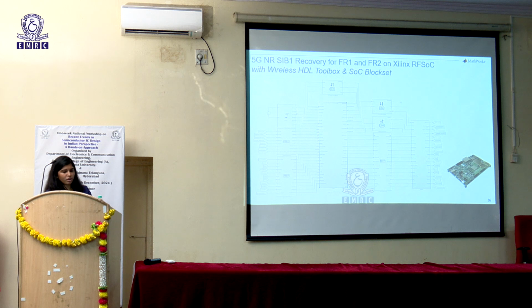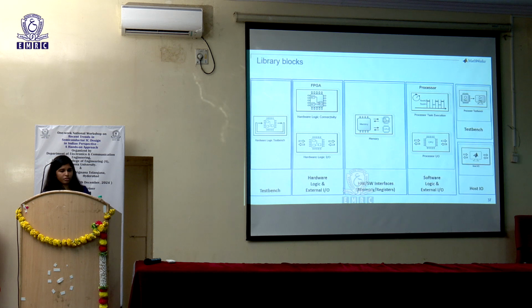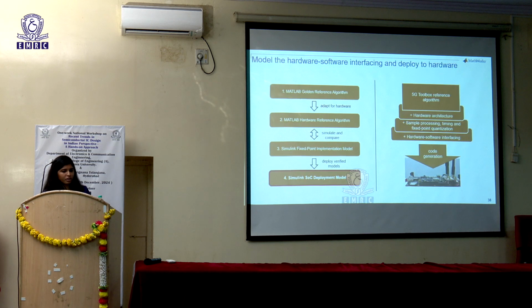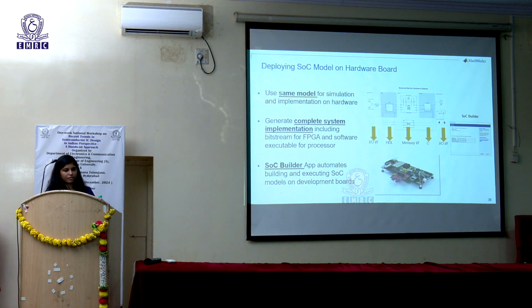This interface model is critical for us because it will decide the layout on your FPGA. Now I have the interface model, and now is the deployment. You can use SoC Builder, the app here, which will help in automating. Once you feed in the interface model, it will take care of the bitstream generation, all the connections that we have given, and the ports onto the hardware that is connected to your system.